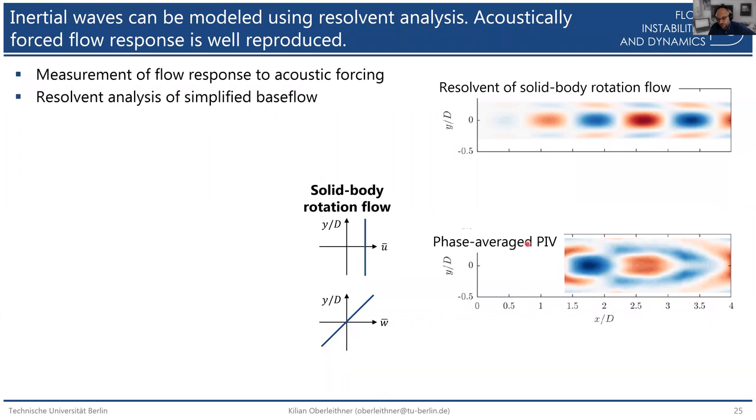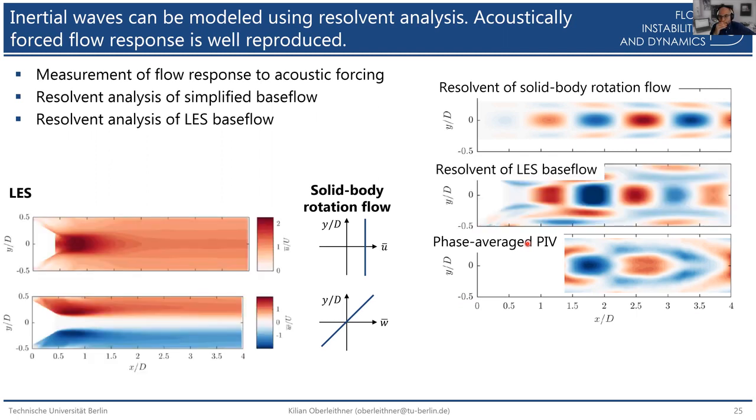So actually this already tells us that yes, inertial waves, which are the only ones that can exist in such a simplified base flow, are actually responsible for this type of response. Then we did an LES study because we wanted to have the realistic base flow and not the simplified base flow. And we did a resolvent analysis on this realistic base flow.